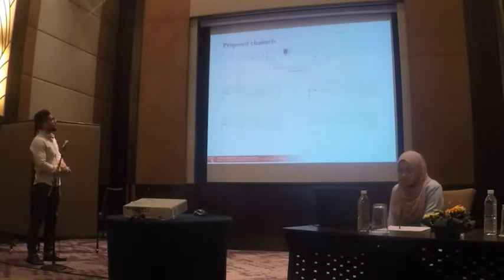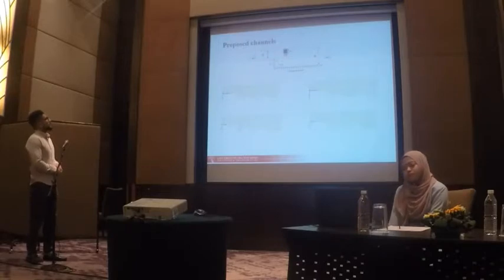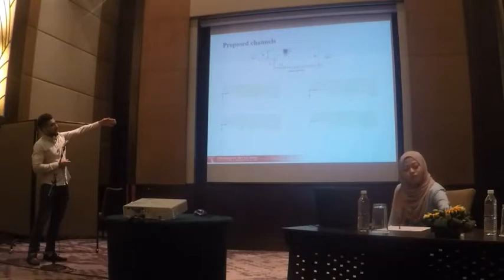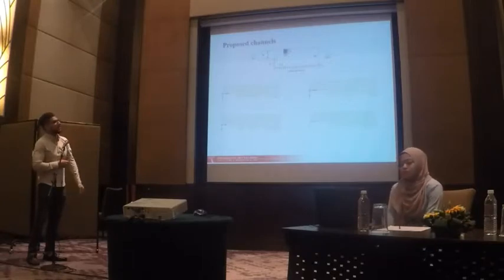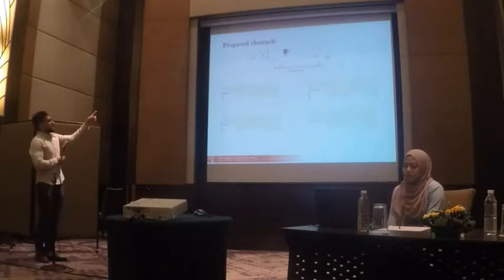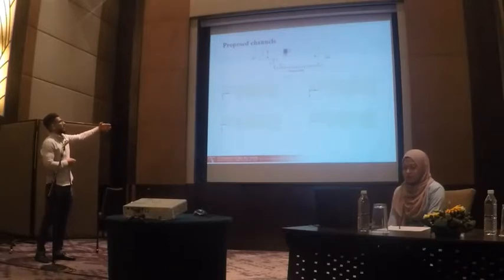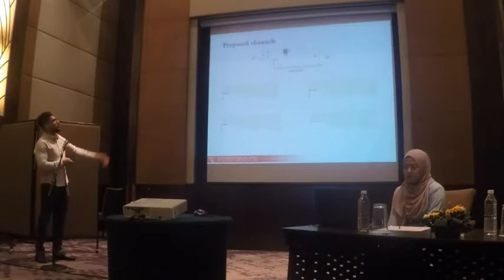All right, this is the proposed channel from the literature that we made. From the literature we found a lot of channels proposed and used for heat transfer. From recent studies, they use the facing step with the corrugated, and the facing step with the trapezoidal. So the proposed channel will add a baffle to the geometry, and we believe that this baffle is going to enhance the heat transfer since it will increase the vortices.